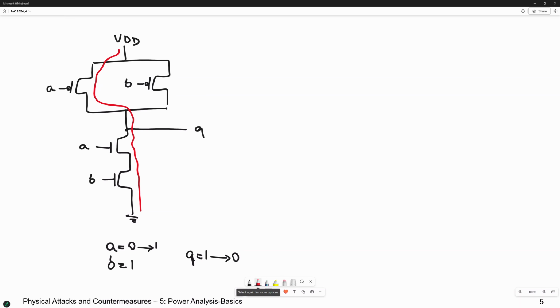And part of the dynamic power consumption comes from this. We do not deal with this, but VLSI, very large scale integrated circuits, engineers are able to actually minimize this by changing the threshold voltage. Because, I mean, you probably have not learned this. Every one of these transistors has a threshold voltage. PMOS transistors have their own threshold voltage. NMOS transistors also have their own threshold voltage. And then you might be able, by changing the type of transistors, to minimize this short circuit current.